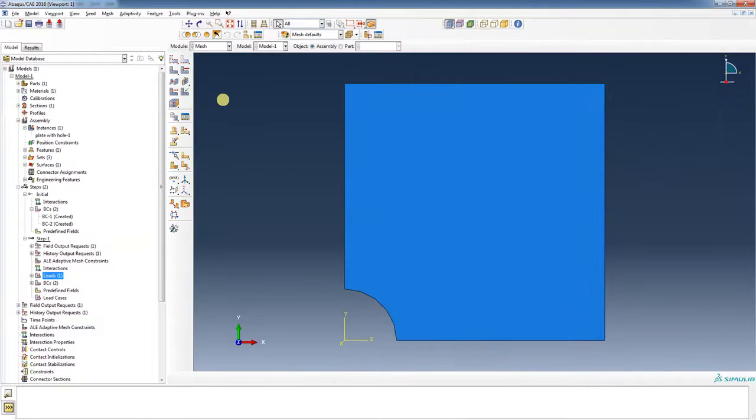All right, let's see what's after load. After load is mesh. Okay, so we're going to use an auto meshing feature that's in Abaqus. In general, auto meshing features are very convenient. However, they can introduce what I would call questionable quality elements into your mesh. Now, we'll get into a bigger discussion about this in class. But these lower quality elements are usually not a problem if they're away from where you are interested in calculating your stresses. So we want to make sure we have nice looking elements at the edge of our hole. Away from it, maybe we don't care so much.